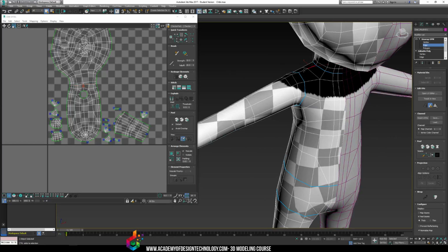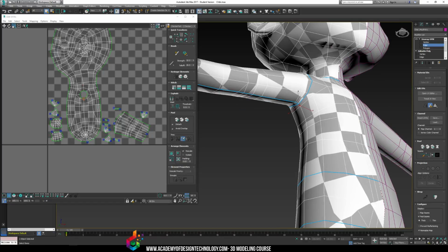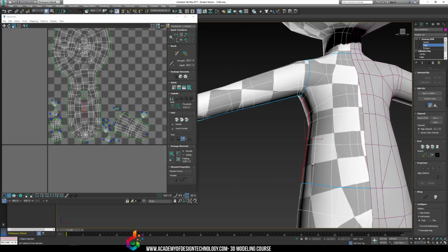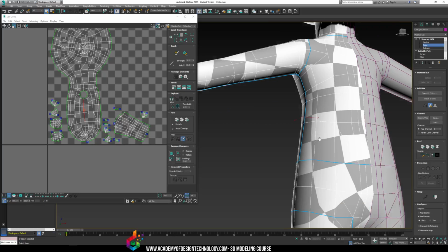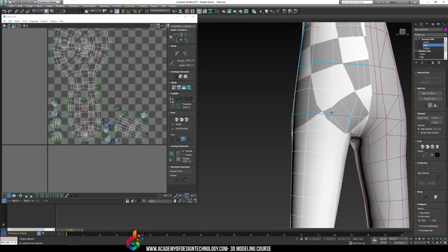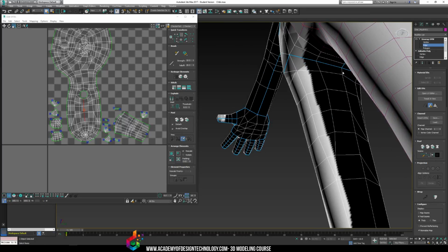And then I'm going to cut the front and the back of the body off by adding 2 more seam lines. I'm going to continue the seam line from the arm here, bring it down the side of the body, like that. And that's where my seam line will be for here. And then going down to the legs, this should actually be fine on its own. And then I create the seam line here. And I'm actually going to continue that seam line down the side of the leg to the ankle, where I'm actually going to cut off the legs.